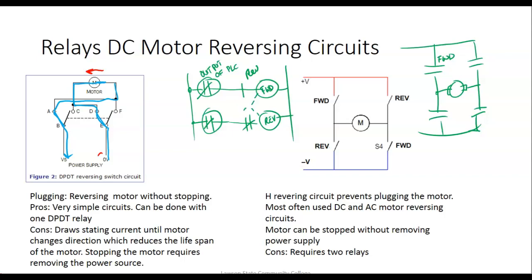But you can always see each time when it comes back, it stops, and then before you can do what? Before you can change direction. So we don't plug the motor. So plugging the motor is when you do what? When you reverse its direction, because reversing forward to a motor is relative. It's relative to how the motor's hooked up. So in one situation, clockwise could make it go forward, but in another situation, clockwise might be reverse in your application, right? So a motor turning, there is no reverse and there is no forward on the motor itself. It's either going to run counterclockwise or clockwise.